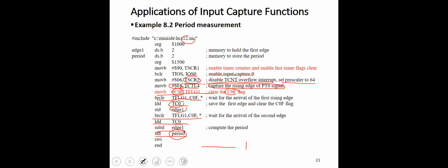And as we said, these two edges might fall within the same window of operation for the timer before it overflows, or in two different windows. But even though when you subtract, in this case, it is modular subtraction. So you basically count how many jumps you need to reach if you go from T1 to T2.